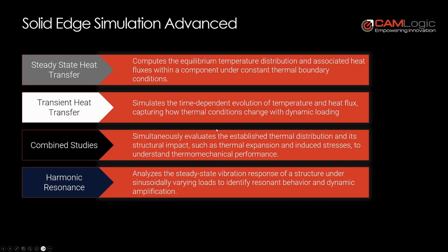Next, I wanted to take a look at Solid Edge Simulation Advanced. So this has all the same capabilities that Simulation Standard has, but in addition, it includes steady state heat transfer, which computes the equilibrium temperature distribution in a steady state. It also looks at any thermal stresses in the combined study.